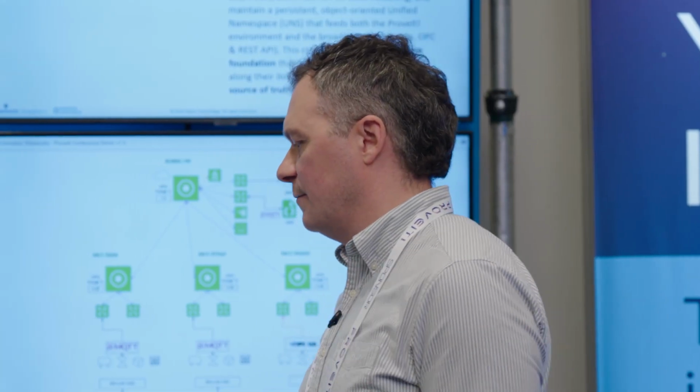Those are all persisted, right? So we are egressing that as per the challenge requirements to the UNS here with MQTT, but we could also view that model tree or those objects in OPC, or we could access our RESTful web API and see those same objects expressed, right? This persistence is an important piece.